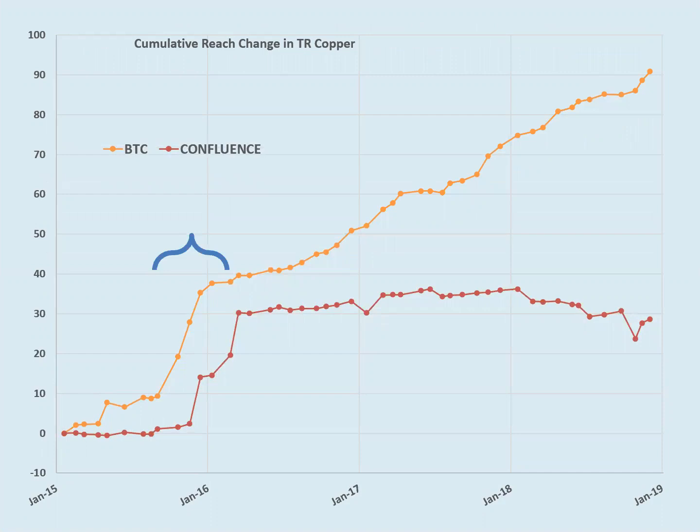But I want to draw your attention to this short period of time here. And we can see that there's a big step up right at that location. Right at that period of time that corresponds to work they were doing at the end of the subdrain where the pump vault is. So it was an operational change for a short period of time.